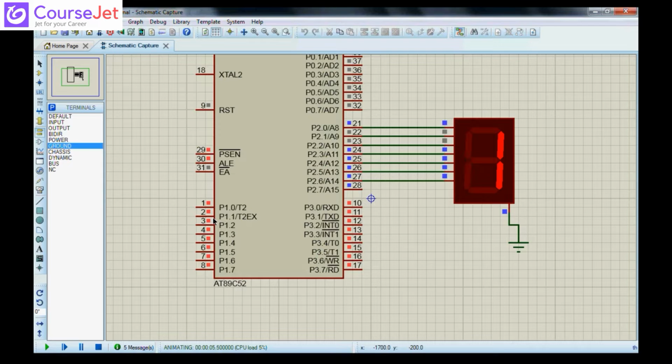So this is how we need to write it. What we are doing is giving output pins, which pin has to be 1 and which pin has to be 0. So we are controlling it by giving our port output. And same here also, you are not supposed to connect it directly without resistors. We need to connect them to protect our device.